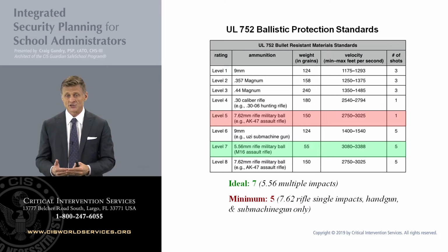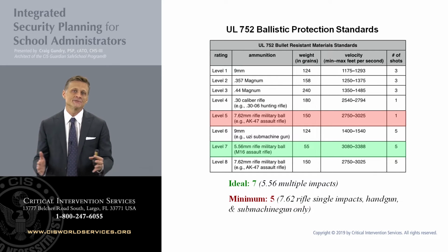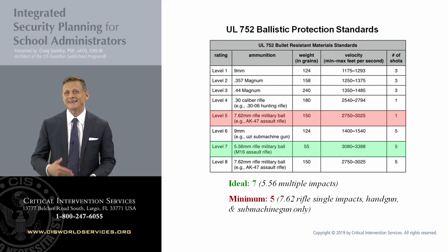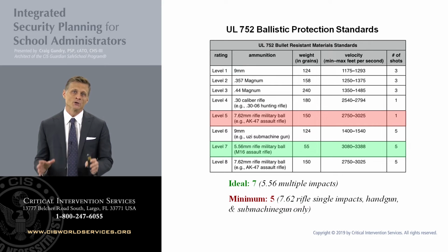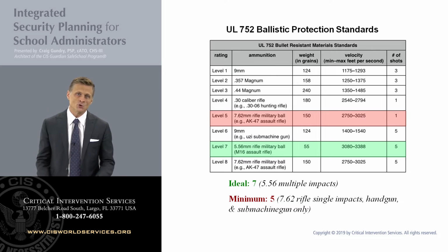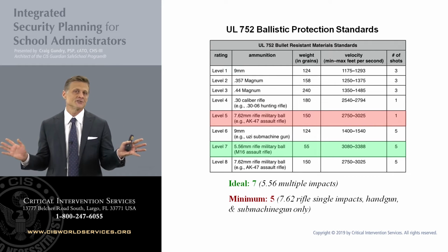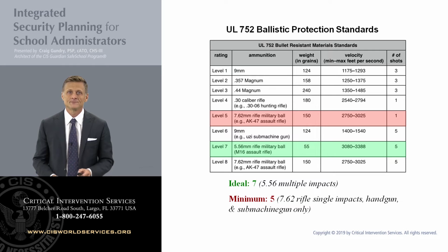Well, the problem in this situation is, because of the dense group of people that were all packed into this very tiny room, a gunman did not need to get into that room. All he needed to do was fire directly through the door and could guarantee hitting targets on the other side. So in that situation, I did recommend installing a ballistic resistant door for that safe room. But trying to upgrade every door throughout a facility, every door vision panel, every window, it just doesn't make sense. Instead, I prioritize intrusion resistance first.